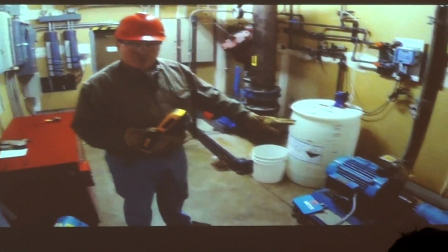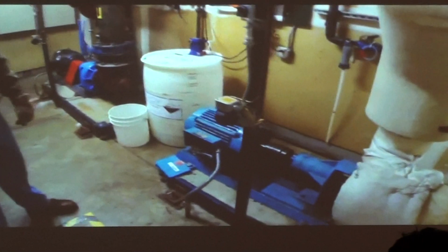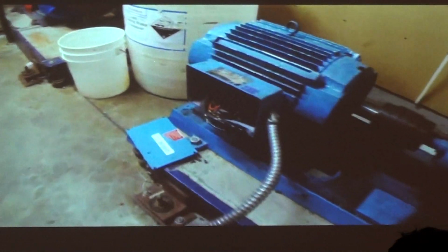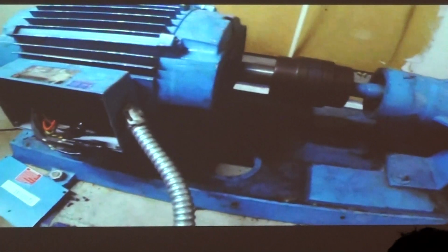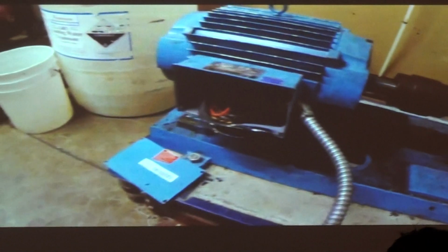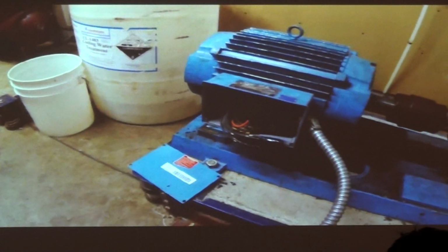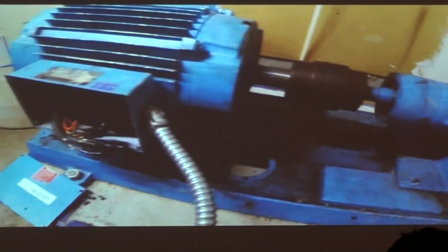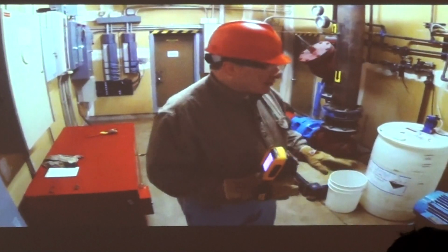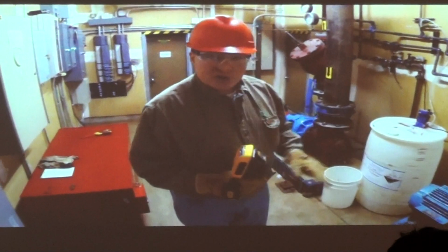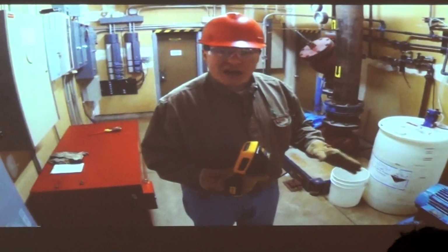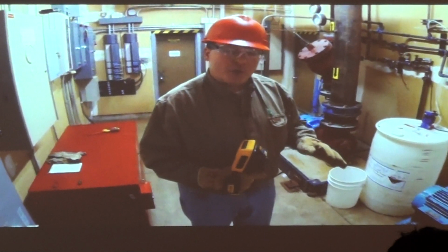Here we have an electrical motor coupled to a pump. The work that we've done in advance, obviously you can see that we've removed the shroud over the coupling and we've removed the cover over the junction box, the termination box. Need to have direct line of sight with thermal imaging in order to do a proper inspection. The first thing that I generally like to do is I'll take a look at the overall motor, the housing itself, and I'll be looking for unusual hotspots or localized hotspots that I wouldn't expect.